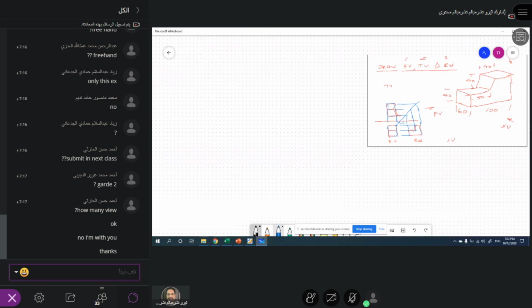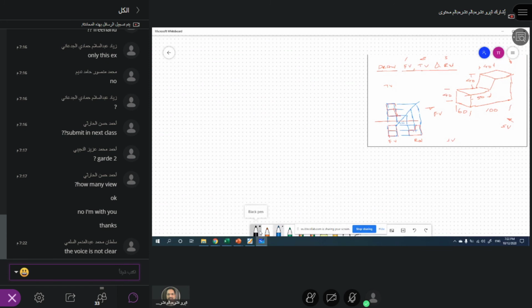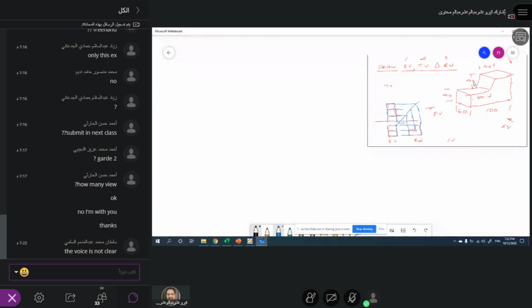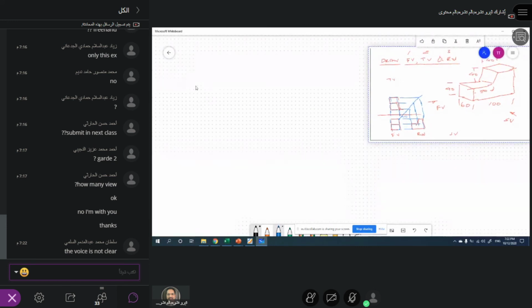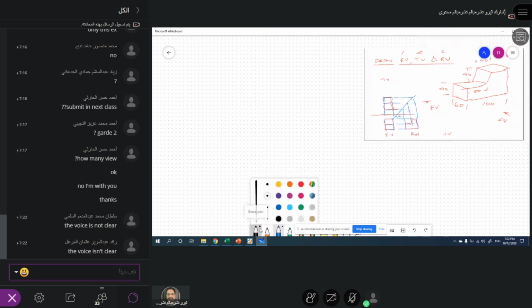Everyone, watch very closely. You understand? Are you here with me? For those who still have some doubt, please watch again. The question given is to draw the front view, top view, and right side view of this given object. What you should do first, take your A3 sheet, put the margin, divide it into 4 equal parts, and in one of the parts you draw it, because it's a very small component, so it's easier for you. Now listen very carefully.